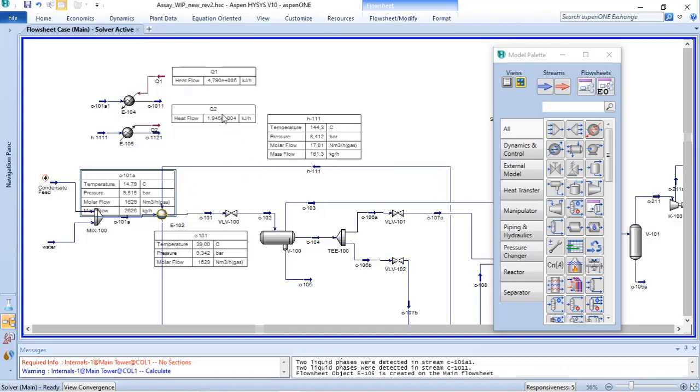And another thing that I verified was, instead of defining the outlet temperature, defining the heat flow and seeing which outlet temperature Aspen HYSYS would calculate for me. And when I use this stream to cool down the waste condensate, Aspen HYSYS is not able to calculate the outlet temperature. So this means that it is too much heat flow for this stream to handle.